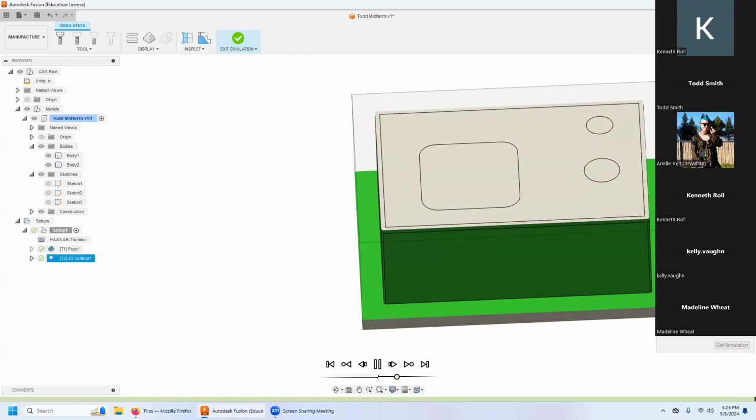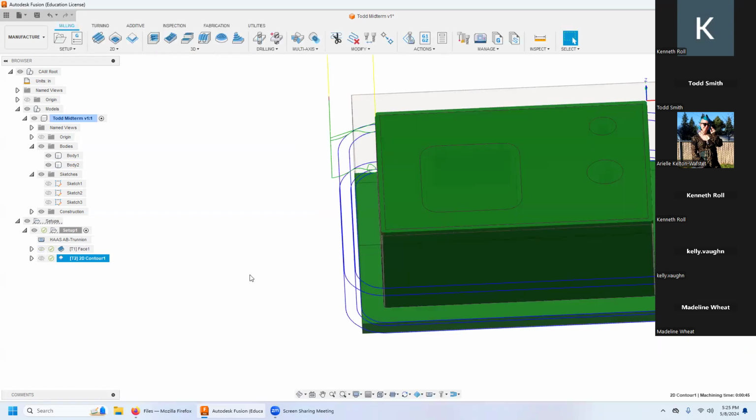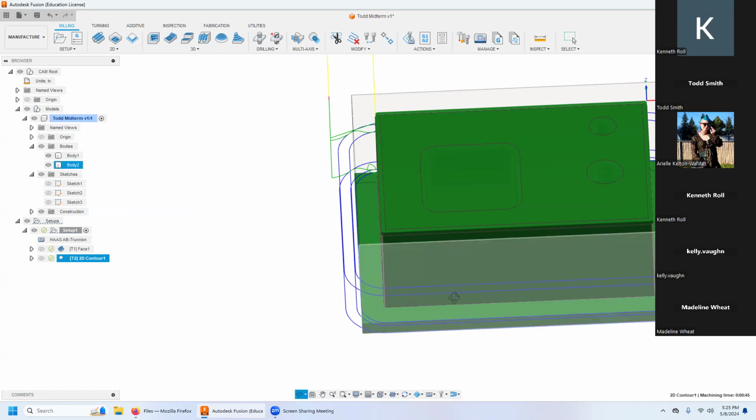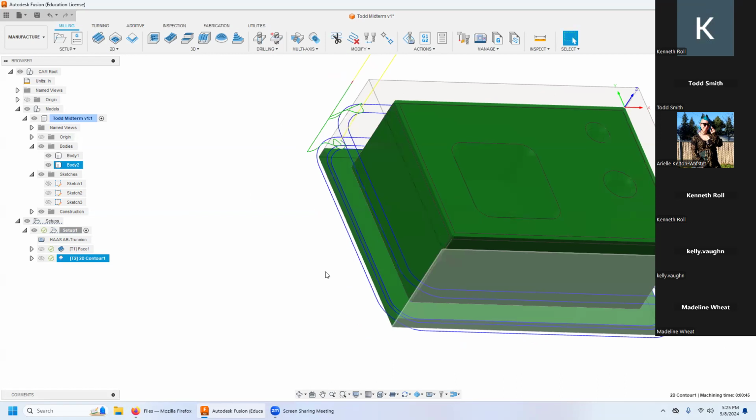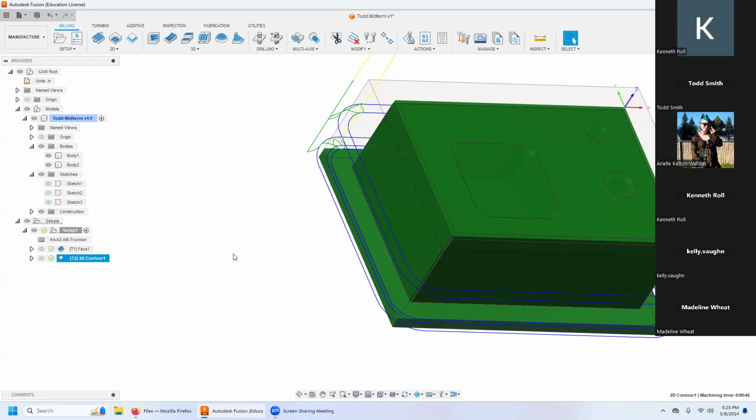I like that tool path. It's very aggressive. That tool path would not survive a flat steel jaw. It would fling, guaranteed. So in our setup sheet, we're going to want to mention the need for a strong grip such as dovetails or mighty bites. Okay.